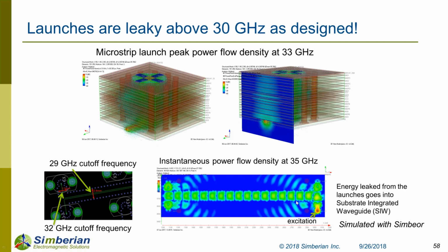Also I can add that, for example, in the launch, because of the layout engineer, not all planes are stitched together. Some of them are VCC, so you have antipads, and in between those layers, in the middle right here, you have most of the leakage, because the impedance of the cavity increases with the distance between the reference planes. So you can inject more noise into the parallel plate cavity.